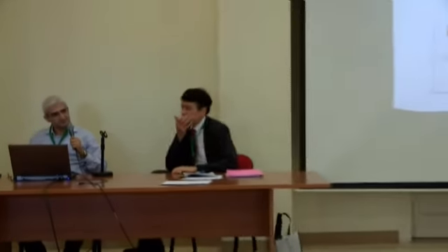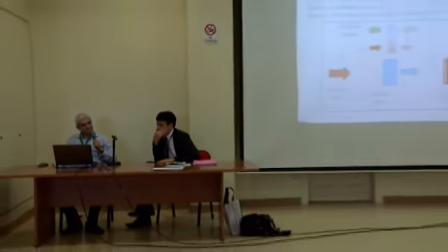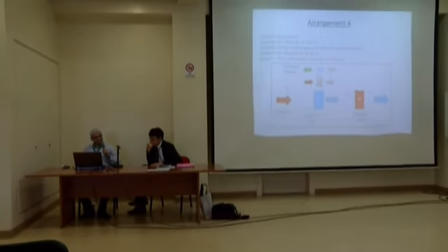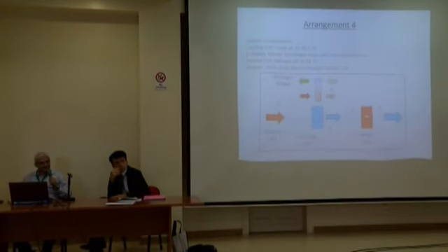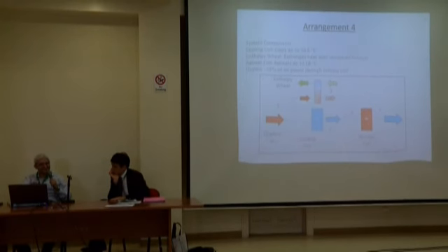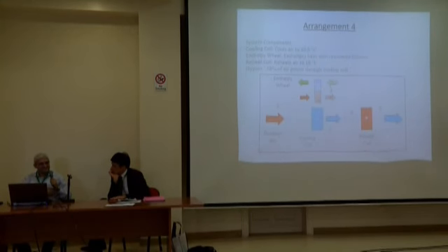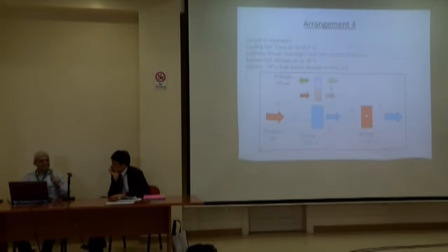Could you please come back to the arrangement? Yes. This arrangement in practice may be difficult because here the thermal wheel is in parallel with the cooling coil, not in series. Yes, these systems were done for a large project, and for this large project it was feasible to go for such a system. It was not for a small-scale project.